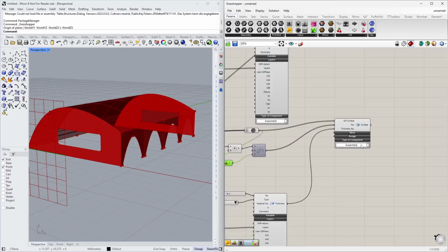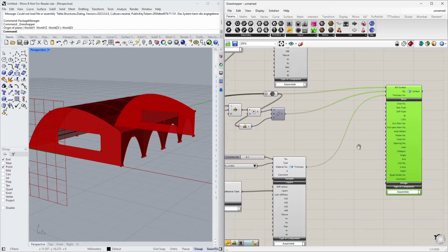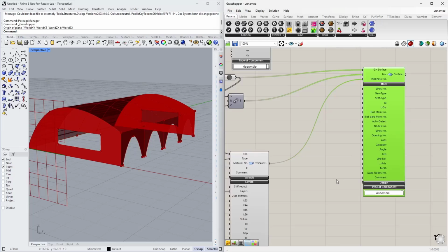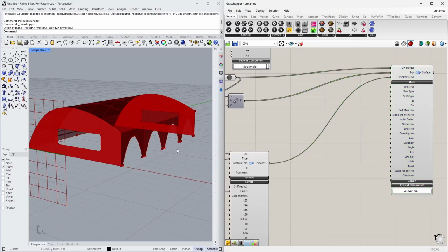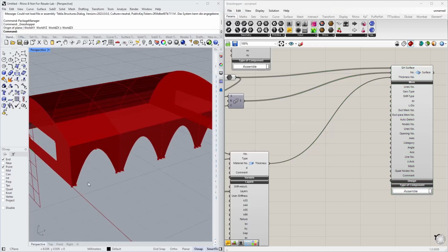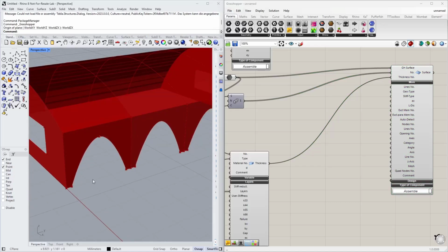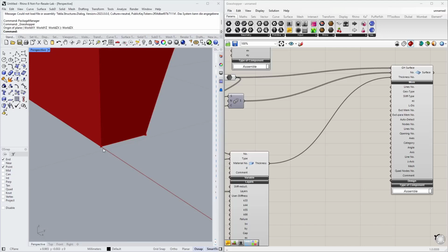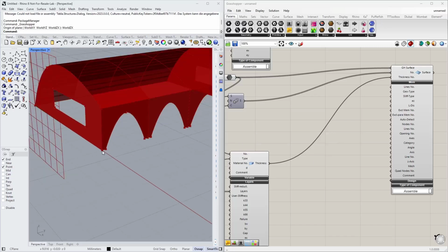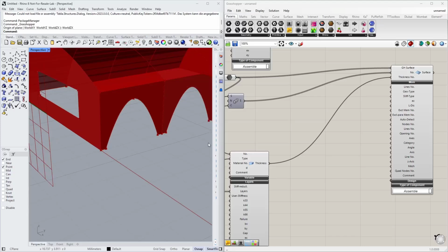That's good. All right. One more thing that I would like to define in here is a mesh refinement. Why? Simply because the default global FE mesh length is 0.5 meter. We have here a distance of about 0.3 meters. So let's have at least 3 elements over this length here. So I would like to use a FE mesh length of 0.1 meters for those wall surfaces.